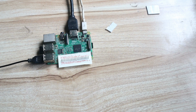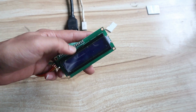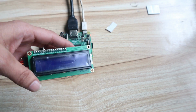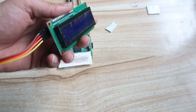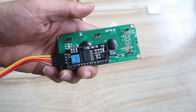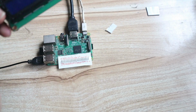Now first we will connect this I2C display. You can purchase this I2C display from Amazon or Flipkart. I purchased it from Amazon. There is already a detailed video on this I2C display. If you want that detailed video, please watch it, you can see the thumbnail on the screen. Here I will just connect quickly. This I2C display has 4 pins at the back: SDA, SCL, ground and VCC. We have to connect all these pins.